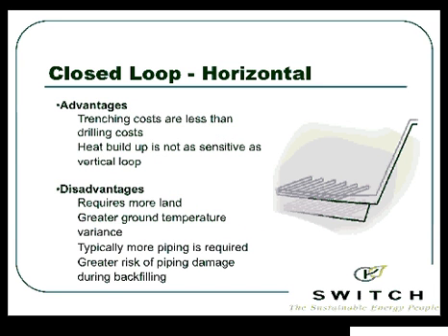Here's a horizontal loop picture. Okay, so now we're trenching as opposed to boring holes into the ground. We're going to trench and put in our system. Of course, if we're not drilling into the ground, we have a lower cost. Heat buildup is not as sensitive as a vertical loop because we're not concentrated in a small land area. We're in a large land area.